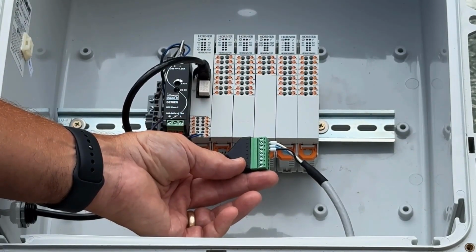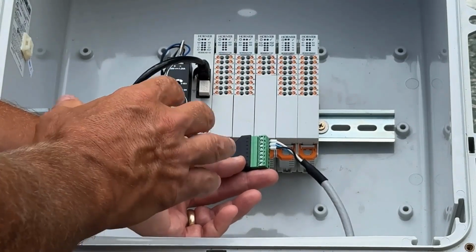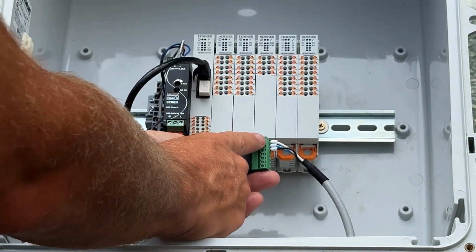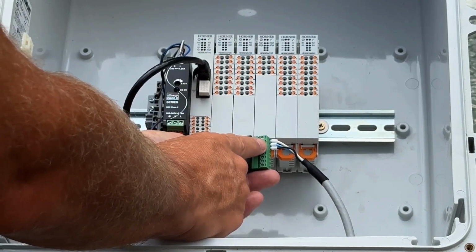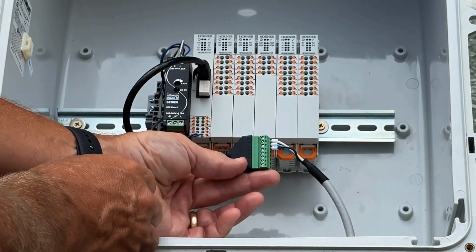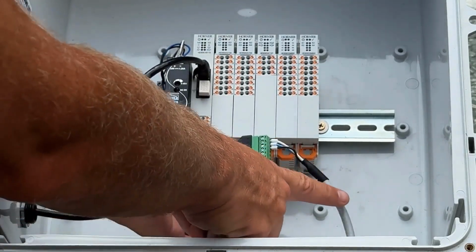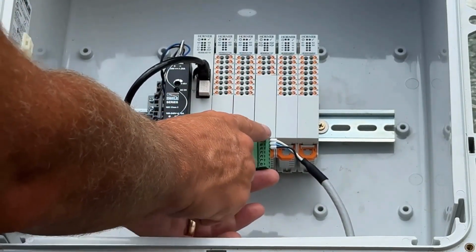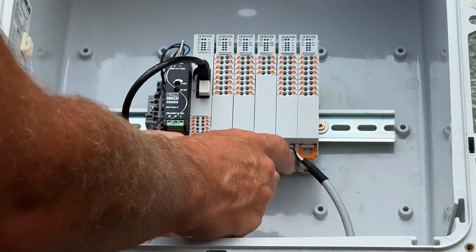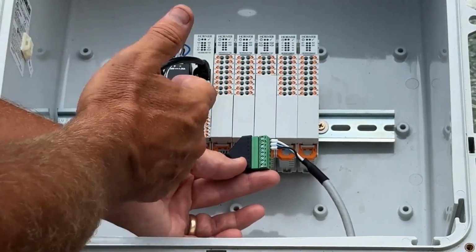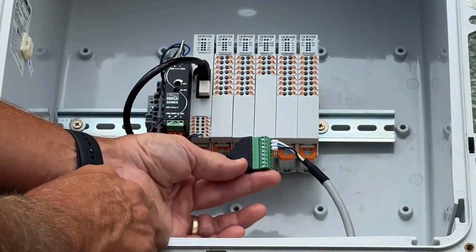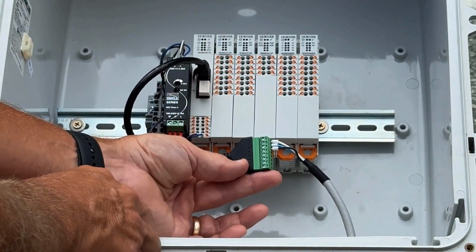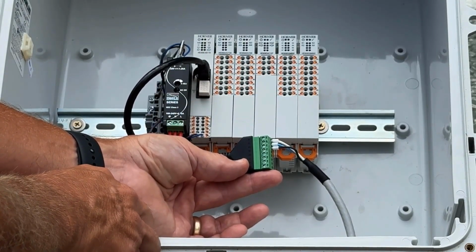Now in this case, we are not running power along with CAN wiring, we are just running CAN high, which is white, CAN low, which is blue, and V minus, which is black. Now it is feasible, and we could run up to 4 amps of power and take advantage of that red conductor in this cable bundle here. But if we did that, we would not connect the red cable to this terminal strip here. We would connect that red conductor to the field terminal strip, or maybe even directly to the front part of the CAN I/O base. So this is a different approach for interfacing traditional CAN wiring with RJ45.